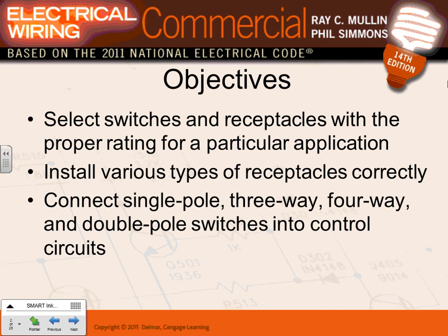When it comes to the switches, most of the time you deal with single pole switches. You're looking at them right in here. These are single pole switches. You can also deal with double pole switches. Double pole switches can switch 2 phases, or 3 pole switches sometimes can switch 3 phases. And you can deal with 3-way and 4-way switches, which you guys are familiar with from the residential.